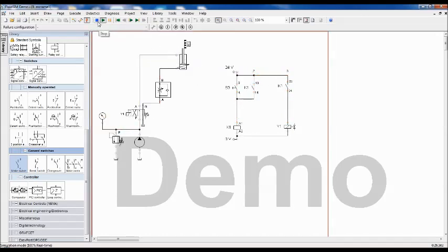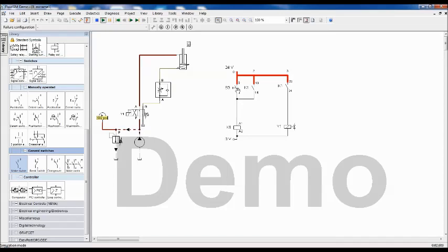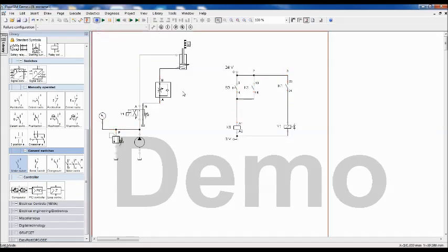So now, to use the proximity sensor in the circuit, see what you observed here. If relay K1 is on, then the solenoid will be on. If the solenoid is on, the cylinder is moving upward. If the solenoid is off, the cylinder will move downward. So the requirement is that whenever the sensor is on, we should switch off relay K1 so that solenoid Y1 is off, so that the cylinder will move downward.